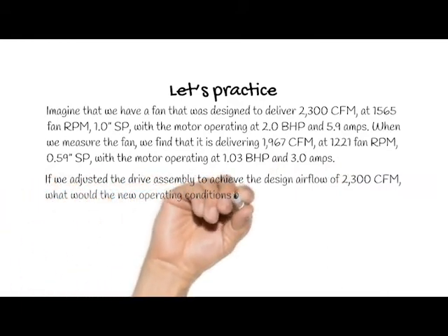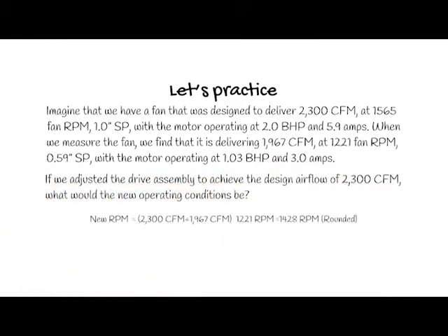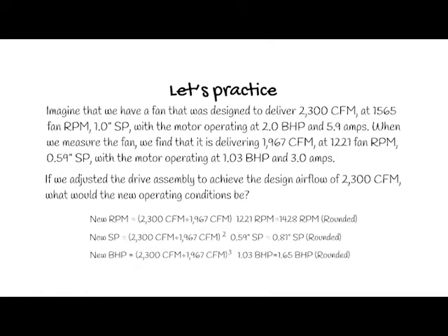conditions be? The new RPM would be 1,428. The new static pressure would be 0.81 inches. The new brake horsepower would be 1.65, and the new amp draw would be 4.8. So let's take a look at how we got these new numbers.